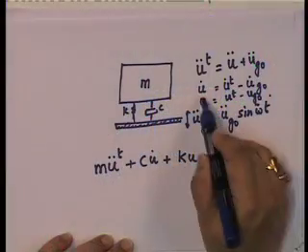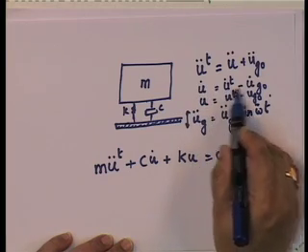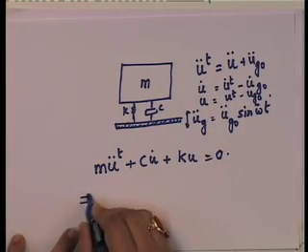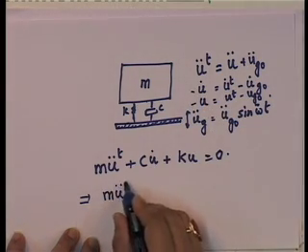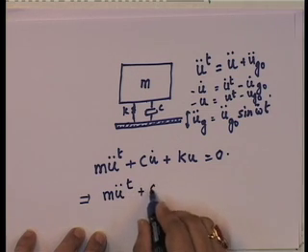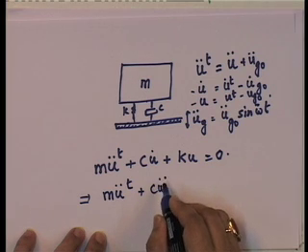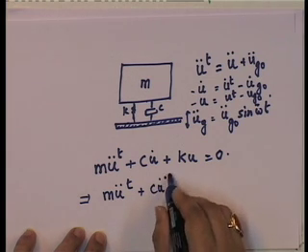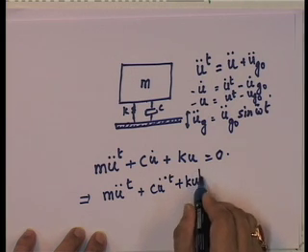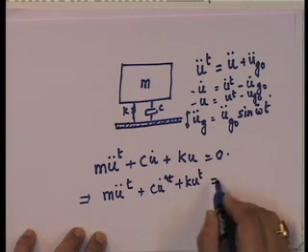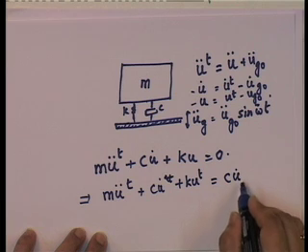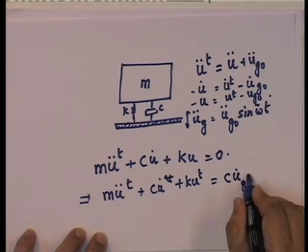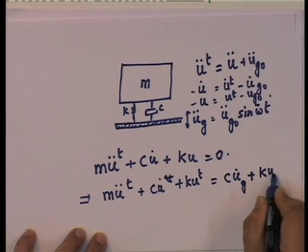Okay. So, if we write it in terms of relative, and putting this in, that u of t is equal to this into this, substituting this and this in here, what we get is m u double dot plus c u dot total plus k u total is equal to c u dot g plus k u g.